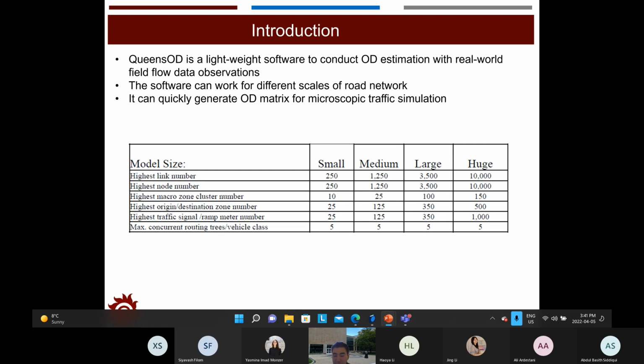We use this information and also do some survey about the trips that those people conduct every day, and build a relationship between these socioeconomic parameters and employment parameters with respect to the trip rate. And we can either use the MCA or CCA method, or use some linear regression method to find out this relationship.